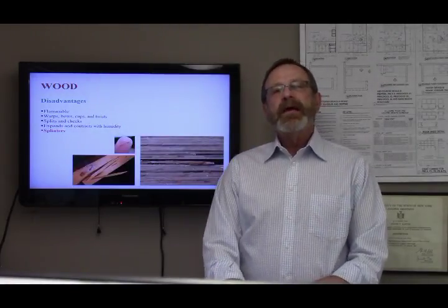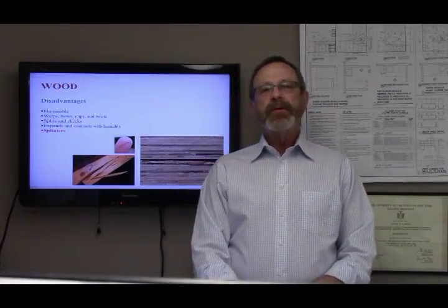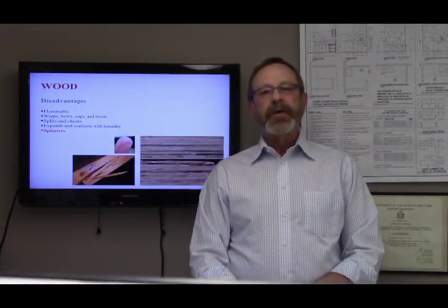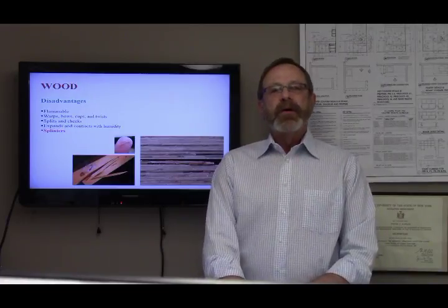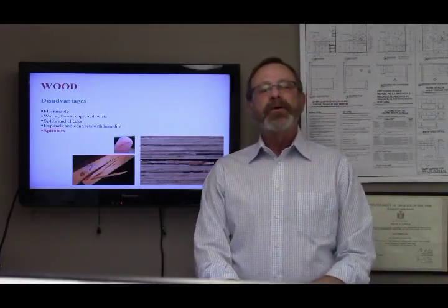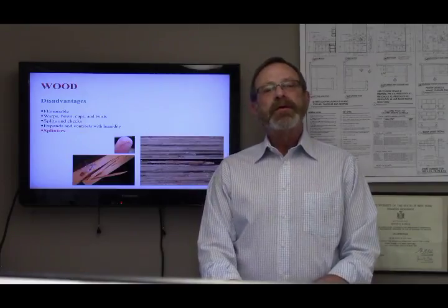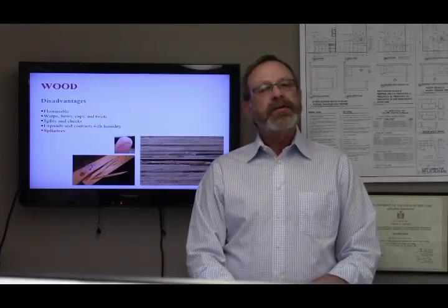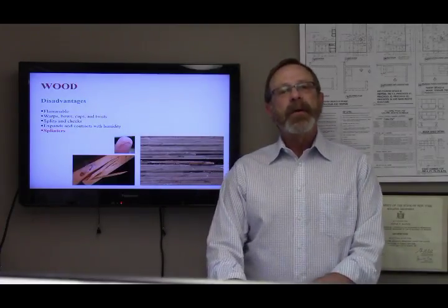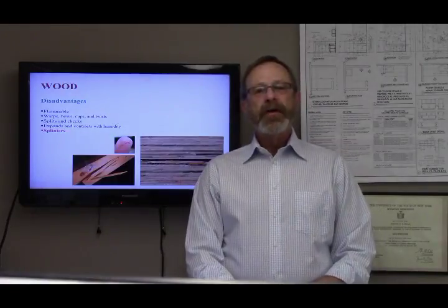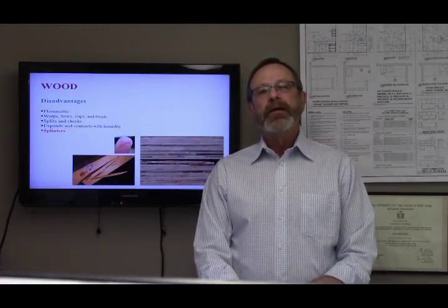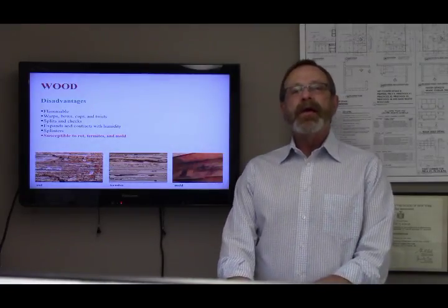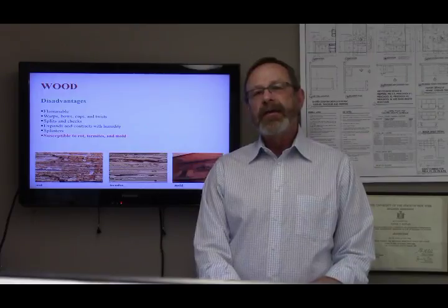If a hardwood plank is not cut properly, it can splinter at the edges. Over time, the finish on a hardwood floor can deteriorate. Without a protective finish, the wood becomes hypersensitive to moisture and temperature changes, which leads to splintering. The boards may also loosen and shift slightly each time you walk across them, causing them to rub against each other. Eventually, this will cause the edges to fray and split. Dry rot is a process that eats away at the wood and leaves it brown, decayed, and deformed.